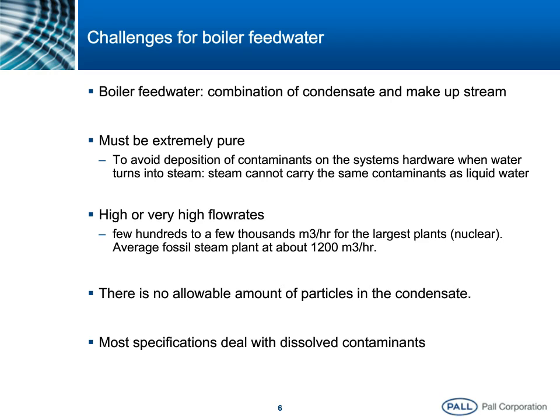So there is really no allowable amount of particles in the condensate. Actually, we'll see that most of the specifications deal with ionic contamination, or at least levels that would indicate that the contamination we would, quote unquote, accept in the system is in dissolved form. So right off the bat, what's the spec for cleanliness in terms of suspended solids? 0.